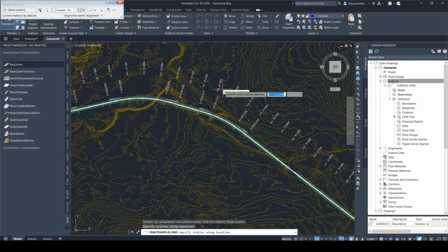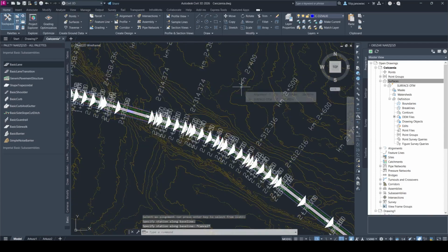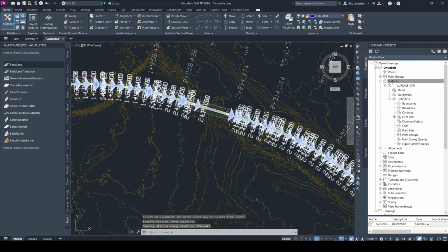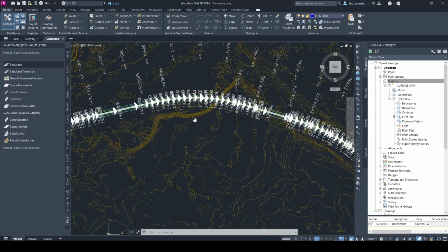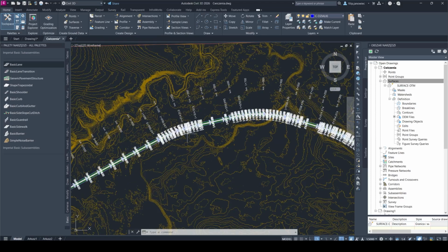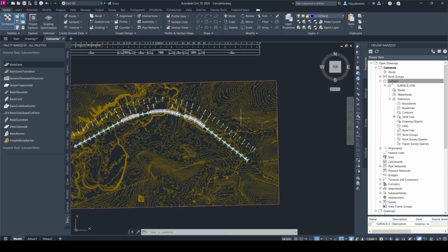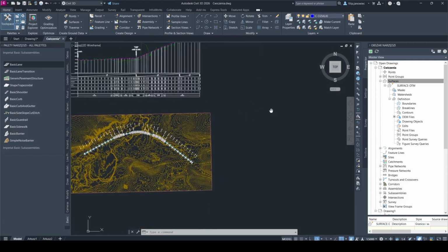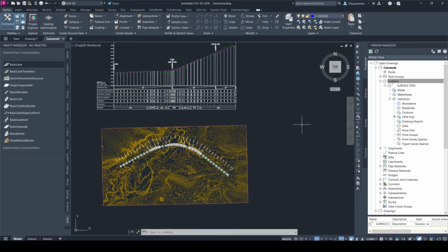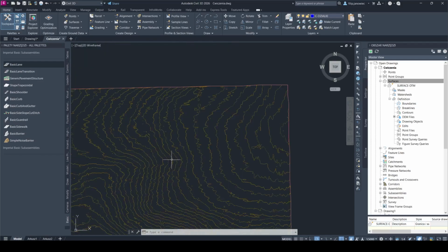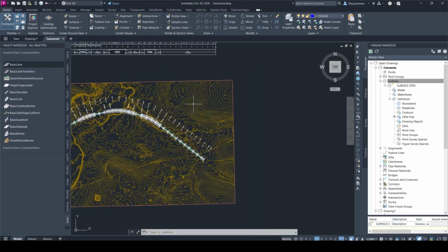And I think after clicking escape, it should appear. So I click escape. Okay. As you may see, these triangles appeared. These triangles tell us that samples are defined, and we can go to cross section. Okay, so what we must do, we must maybe